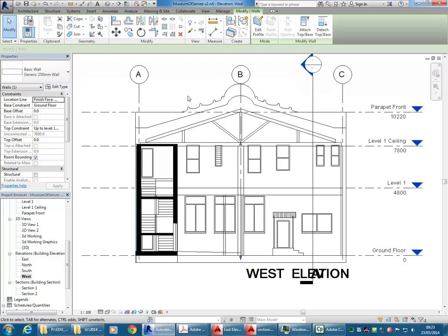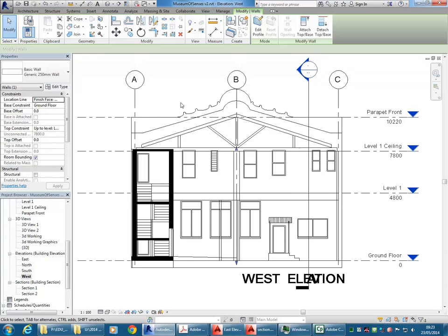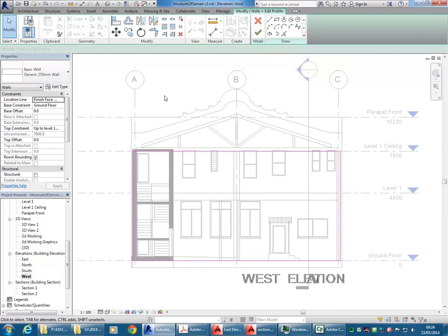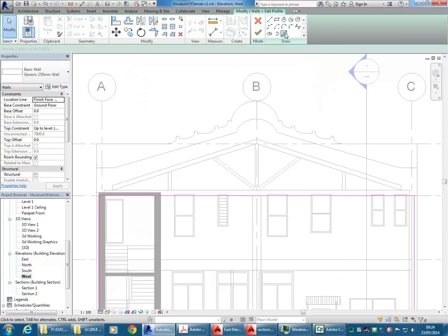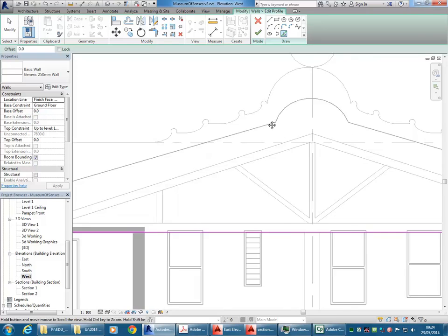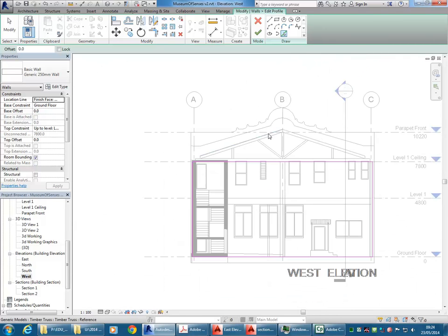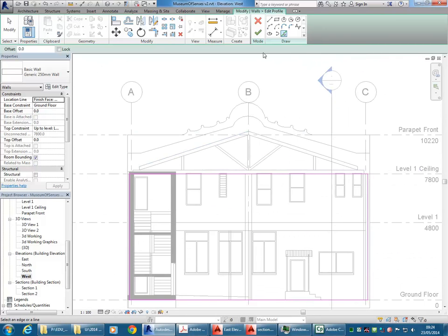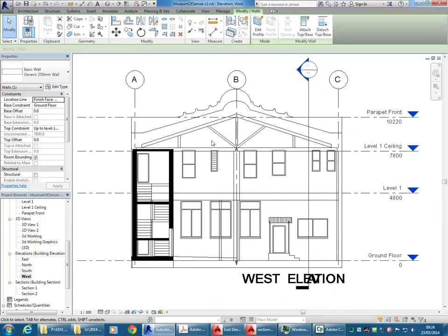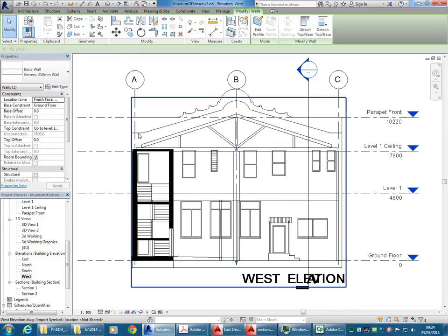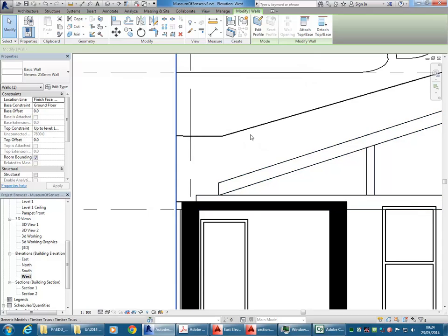Because we've got to think about it as a 2D profile now. This one's fairly easy. So if I go to edit profile, having done all of that, the next part is not as complicated as the first one, using pick lines. I'm going to try to pick these lines, but it's come from Illustrator, so it doesn't want to be my friend. So I'll cancel that first, and I've got the line there, which is the main edge for the top of the wall.